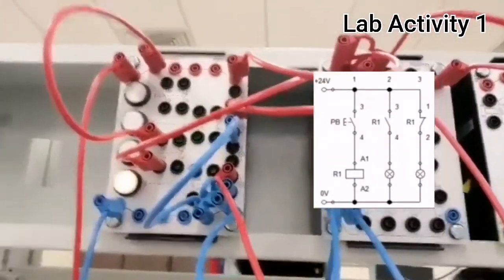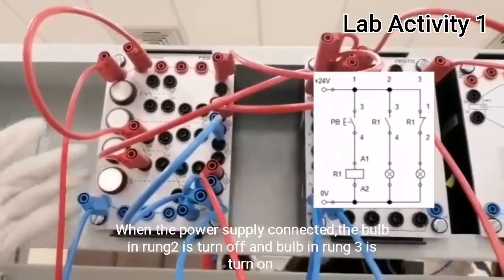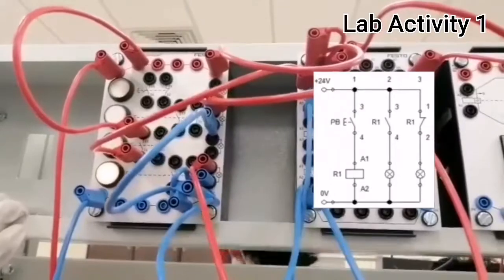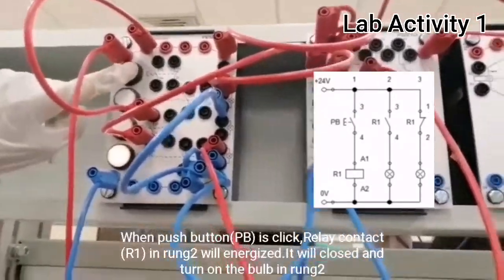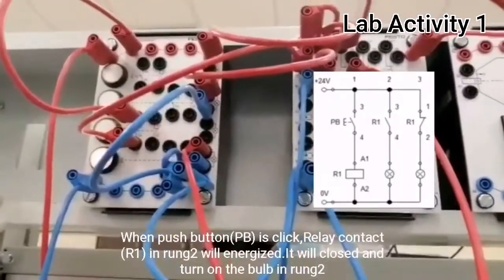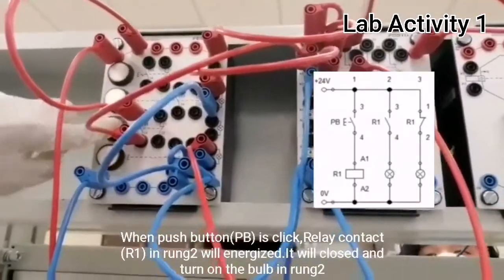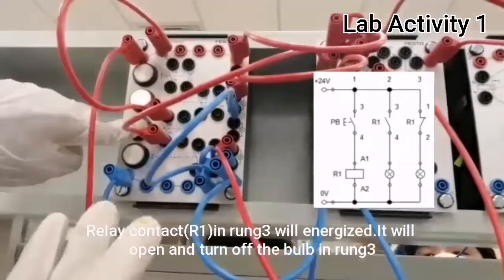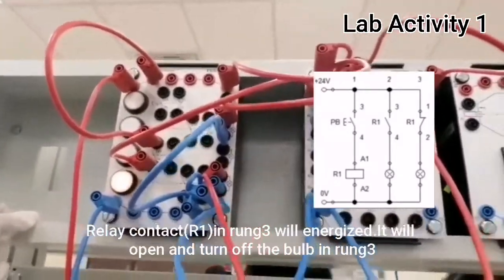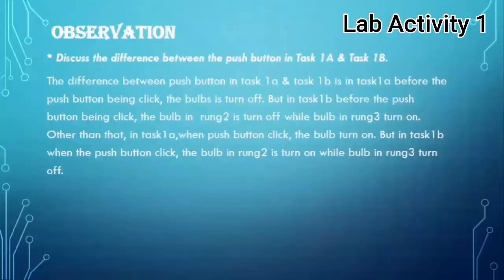Now task 1B. When the power supply is connected, the bulb in rung 2 is turned off and the bulb in rung 3 is turned on. When push button PB is clicked, relay contact R1 in rung 2 will energize. It will close and turn on the bulb in rung 2. Relay contact R1 in rung 3 will energize. It will open and turn off the bulb in rung 3.